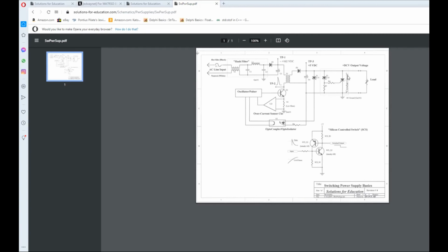This is an SCR. There's a circuit over here, which is a trigger circuit. And if this trigger circuit ever fires, that is, it gets to a particular voltage, and there's a Zener there, if that ever triggers, that means this guy here becomes a dead short. And as a dead short, we're hoping to blow the fuse. The whole reason for doing this is if the voltage gets too high, we don't want to damage our equipment over here.